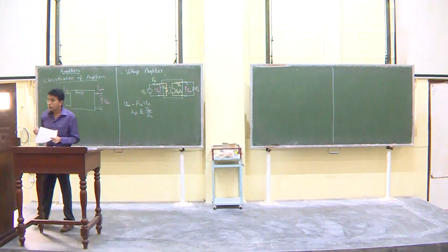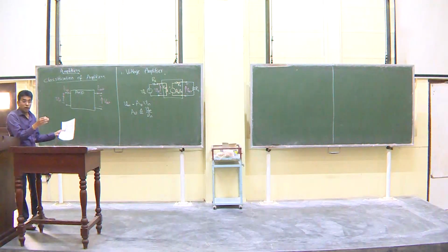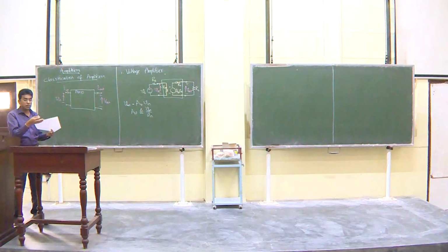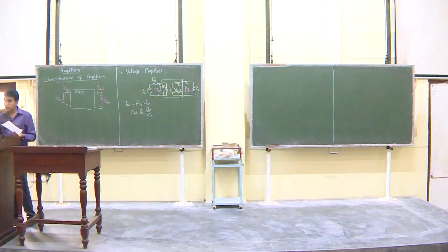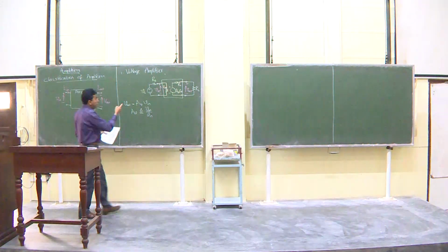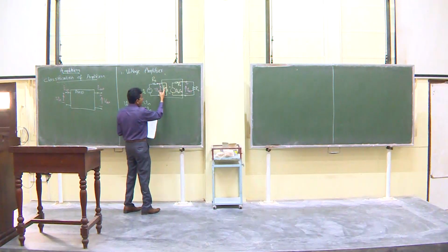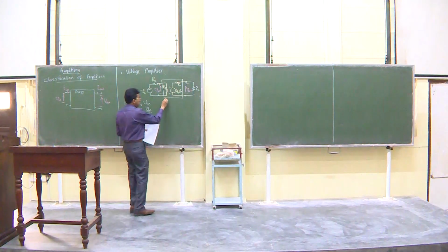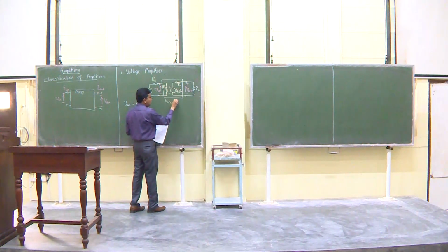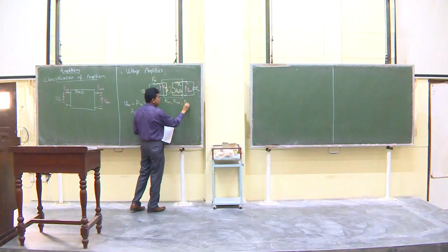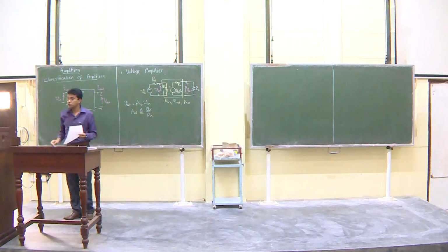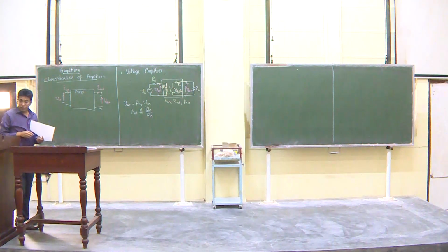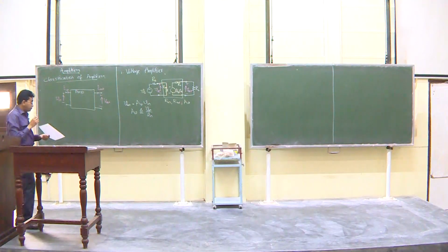So if you look at this particular circuit, this whole black box, which may have hundreds or thousands of transistors, BJTs, MOSFETs, op-amps, whatever it is, is defined by three variables: R in, R out, and AV. That's all you need to know about this black box. Once you know these three variables, the whole thing is defined. Okay?